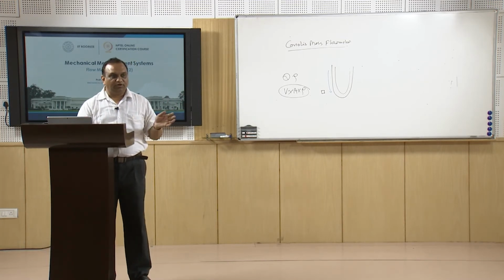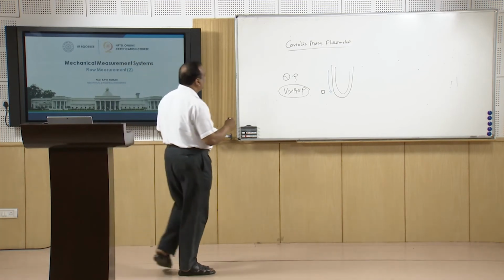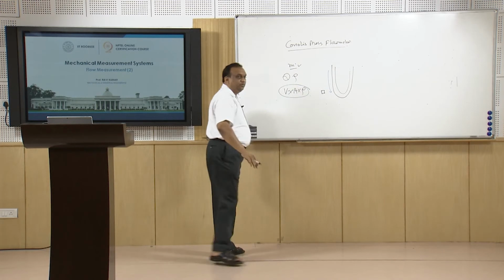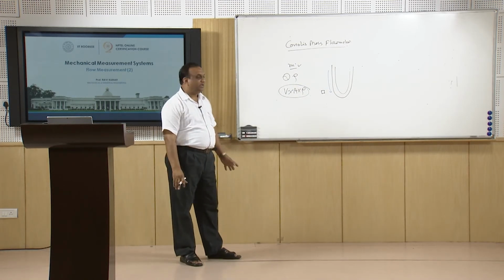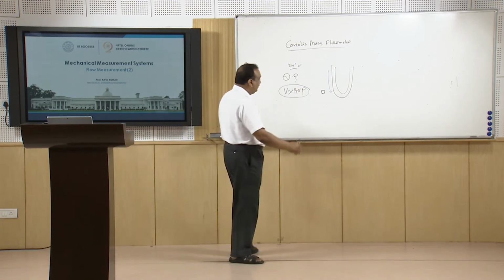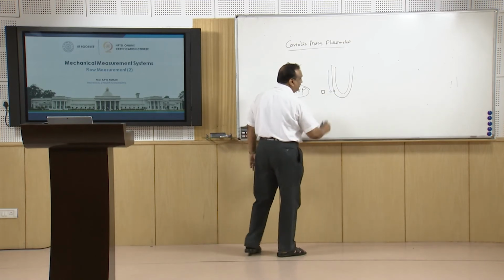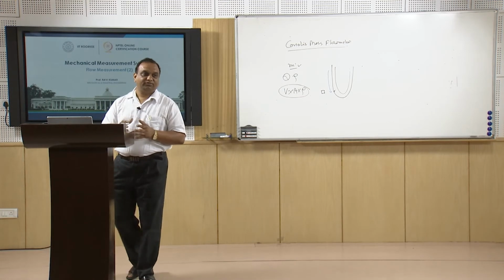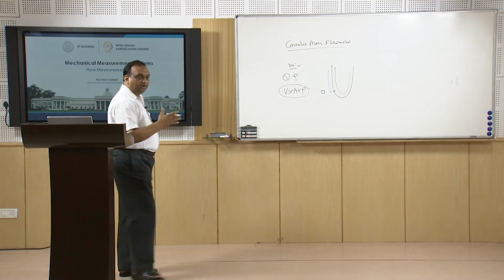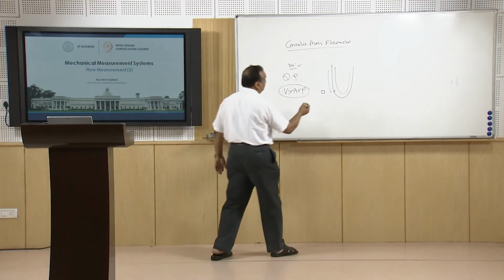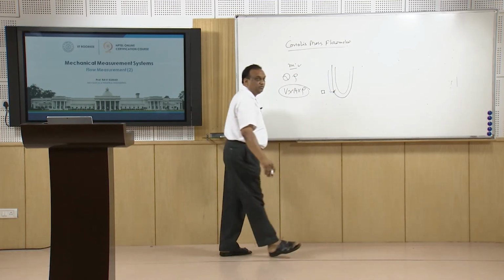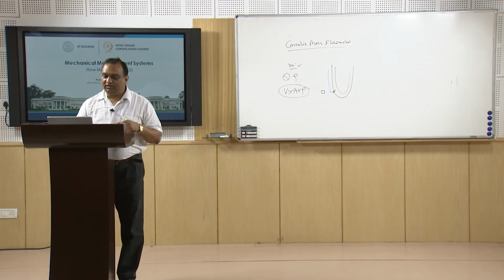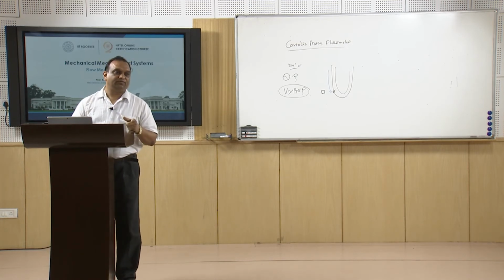So the beauty of this flow meter is it is used for the mass flow rate. It doesn't matter whether it is a liquid phase or the solid phase. But normally, when the liquid phase is more than 10% or 20%, this flow meter has to be recalibrated. So we have to have calibration curves for different fractions of liquid and vapor if you want to have correct measurement of the flow through this flow meter.